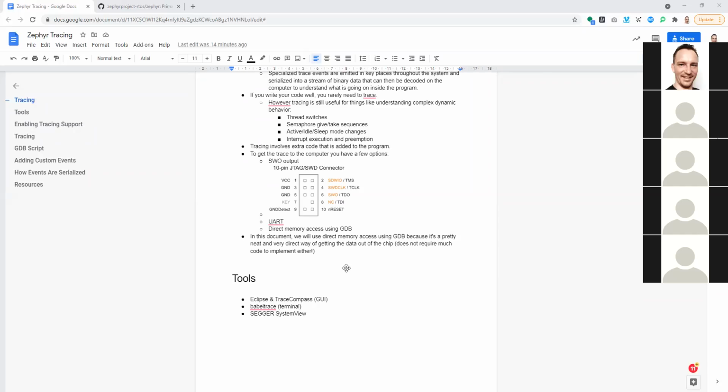And it has an internal first in, first out queue, which caches the bytes that are going to be sent out to the debugger, and your code can continue executing whatever it is doing while the data is being transmitted. So that's very useful. You don't need to use a UART. You don't need to worry about having to spend time in the UART interrupt. The SWO pin handles that for you, so it's very flexible in that sense.